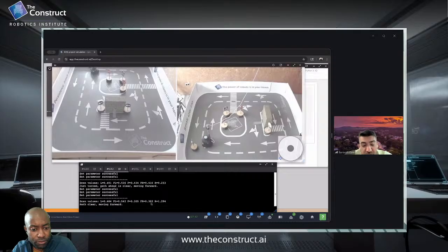So it's very near to my threshold. If I calculate the time to move here, it's 0.302 minus 0.3 divided by the distance. So it's very little time and sometimes it's very short. So on that condition, I put an if condition: if that value is too small, just consider the time to move to 0.05. So with more laser scanners, it's easier to calculate those values and prefer the direction with the highest value and go in that direction.